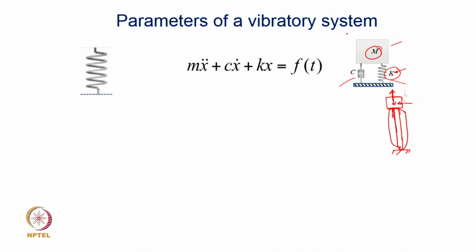So, this spring, as I mentioned, is the physical coiled spring which represents this particular stiffness. Now, what this stiffness is all about is that if I apply a force on this spring, we know very well that it will deflect. So, if it deflects by a distance equal to, let us say, x, and you are applying a force, then a finite amount of force divided by the finite displacement that it generates, that basically is your spring rate, okay, or the stiffness of the spring.